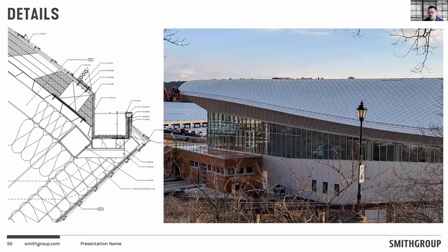And again, on the roof, you need a gutter, and how we can conceal the gutter nicely, following the geometry of the roof curve. There's going to be a snow guard and a snow rail, and you can see from the photos the snow rail follows the geometry with a similar segment. And the snow pads are barely visible from the photo because they all align, at the one point of the diamond shape of the roof tile.